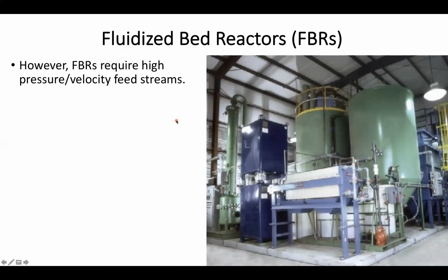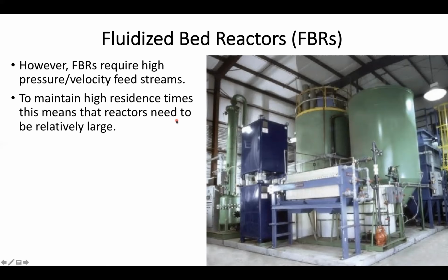However, this does yield some design constraints. Most notably, it's going to require a lot higher pressures and velocities, which means a lot more pumps. And in order to maintain high enough residence times for effective mixing and reaction, it tends to mean that reactors have to actually be a lot larger than an equivalent packed bed reactor, where I've kind of concentrated everything together.